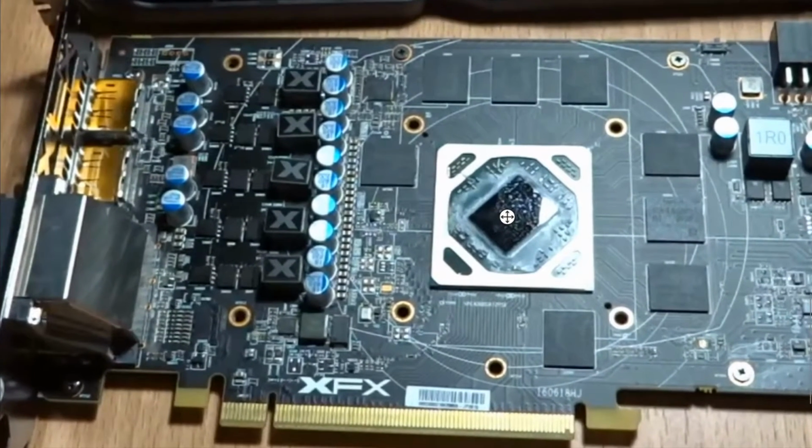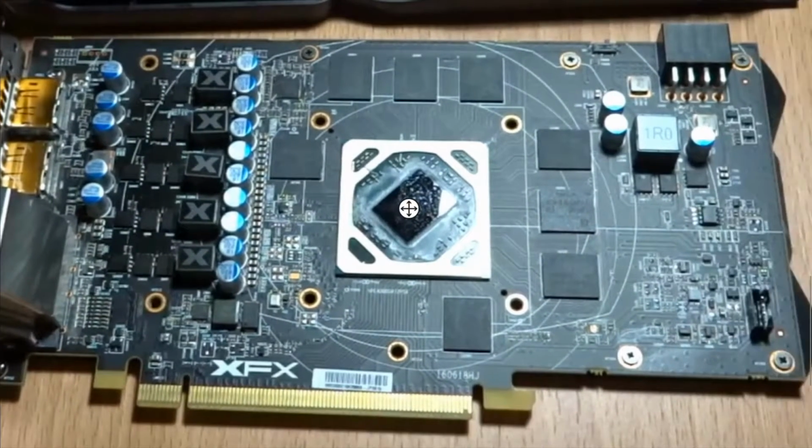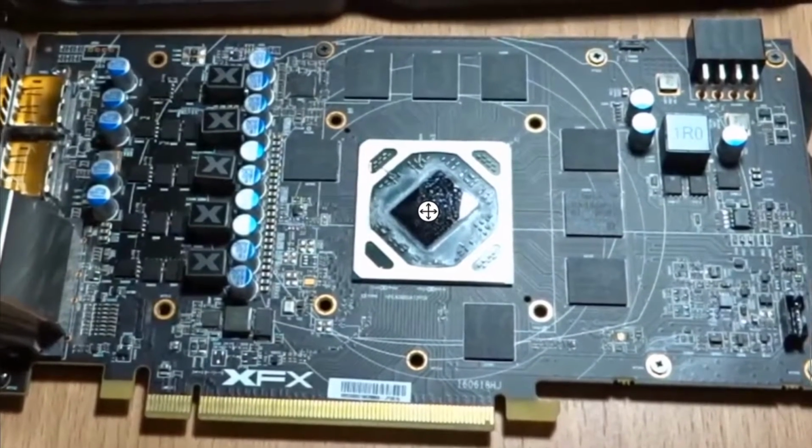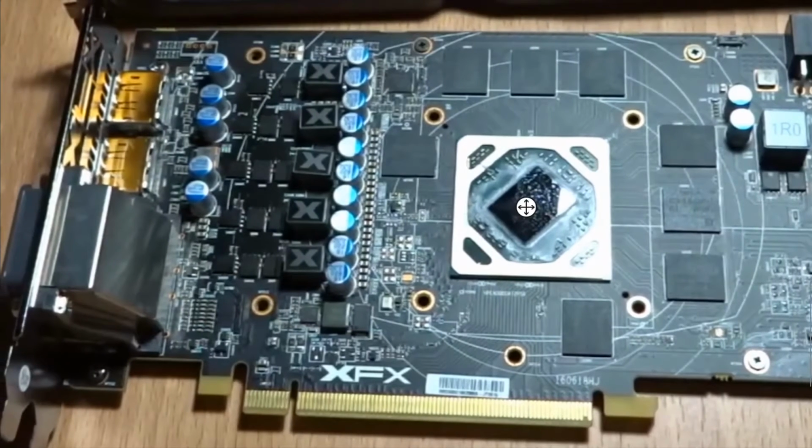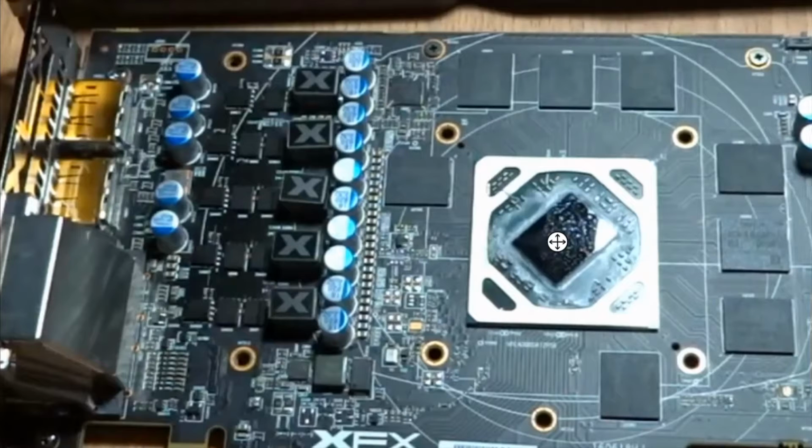And basically at that time I didn't know that AMD cards are actually quite different in some ways to NVIDIA cards. Because on NVIDIA cards, the VMem VRM also powers your memory controller on the GPU. Like on here, there's a memory controller in there somewhere. On NVIDIA cards, this gets powered by the memory VRM also. On AMD cards, this has its own memory rail. I think it's called VDDCI, yeah, I think it's VDDCI.